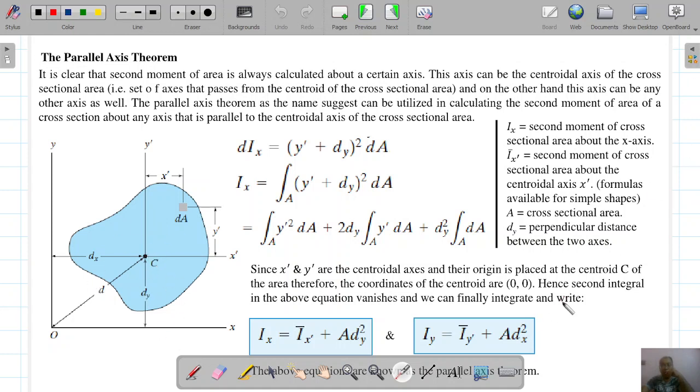So the parallel axis theorem is also exactly the same as the one we have just done. We know what Ix is. Ix is basically nothing but y square, and you know what dA was. Remember, it is y square dA. So dIx about this axis, if you look at it, will also be y square dA. So it is very similar.